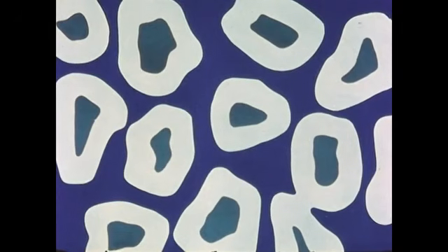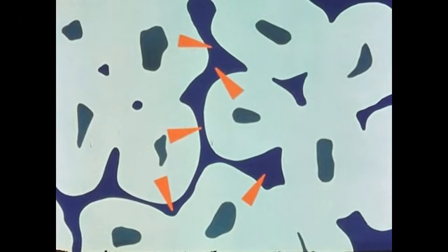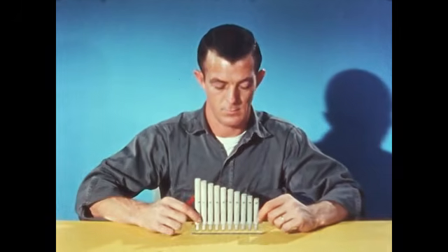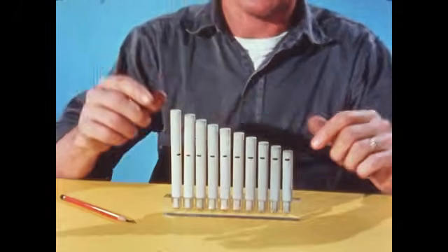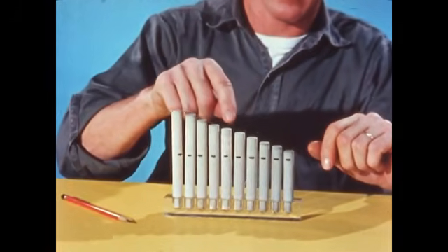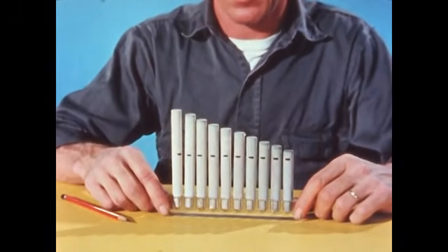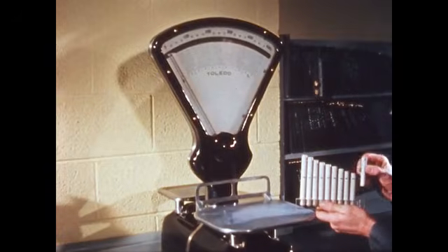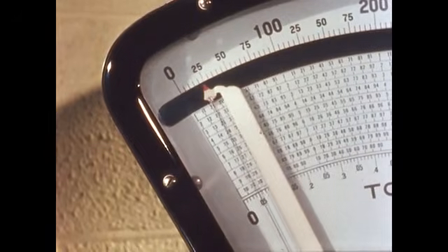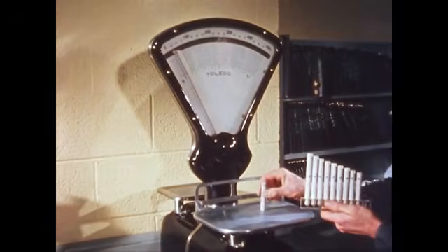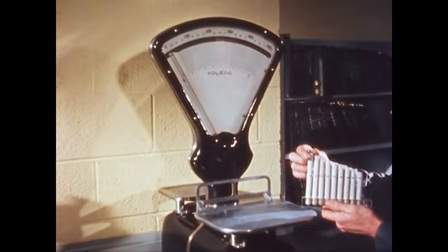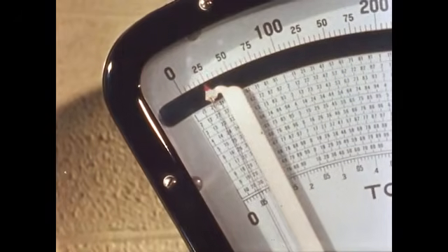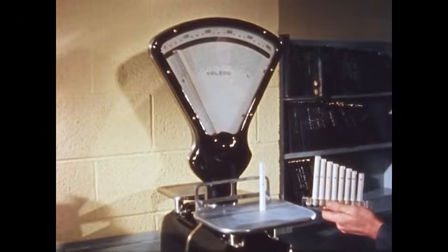Extra water that does not combine with the cement eventually evaporates, leaving pores and capillary passages that reduce water tightness, durability, and the strength of the paste. To illustrate this, cylinders of hardened paste were each made with the same amount of cement, but with different amounts of water. They all weigh approximately the same, since the water not combined with the cement has evaporated. In the shorter cylinders, the cement gel particles are bound closely together. In the longer ones, they were spread apart by excess water, which has evaporated, leaving a honeycomb of voids.